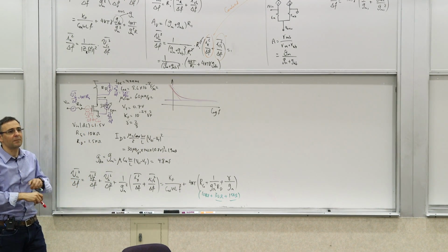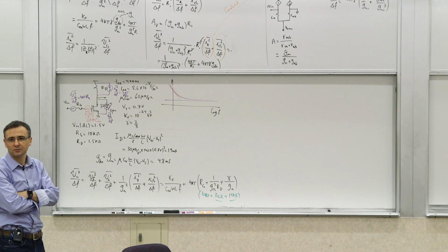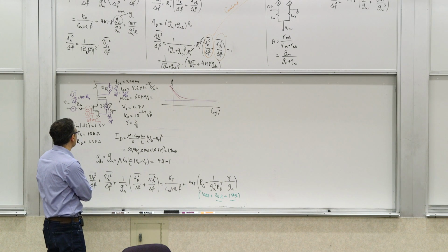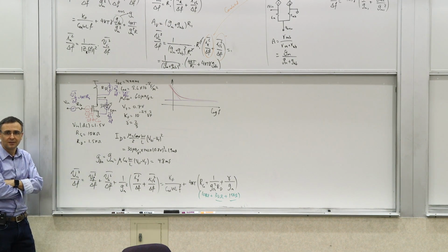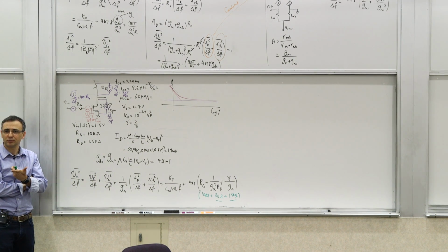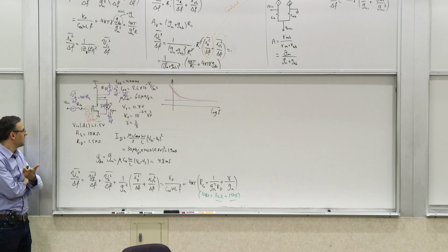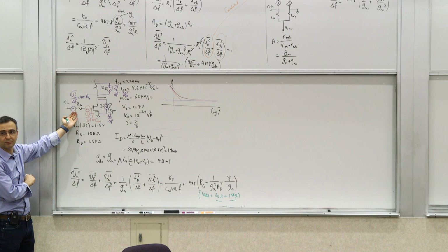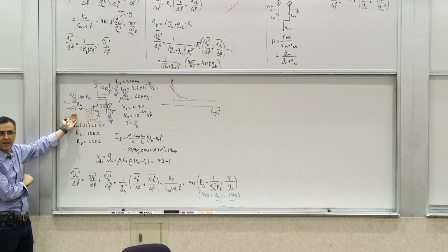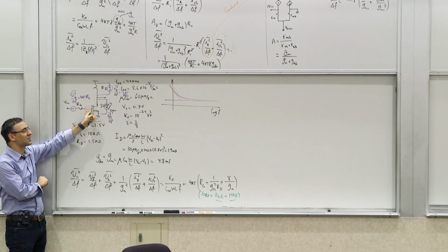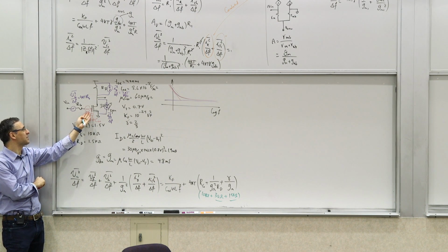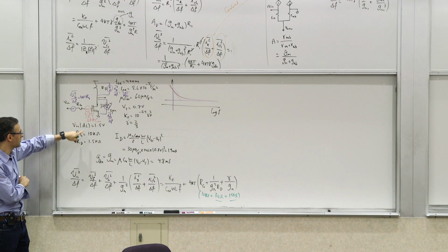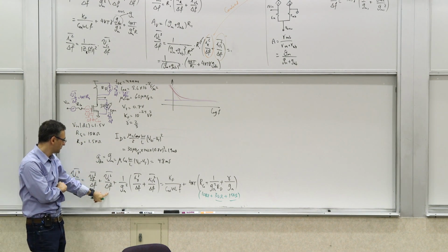What if we have this one capacitor? What would happen to this noise calculation? Well, what would change when you have this capacitor? The transfer function will change, right? Now, these two noise sources, this one is before that capacitance, so this is already at the input anyway, right? And this one, you could argue, well, this is inside the transistor, et cetera. It doesn't matter because it's low frequency anyway. That's not the frequency at which the capacitor is. So these two are not going to be affected by it.